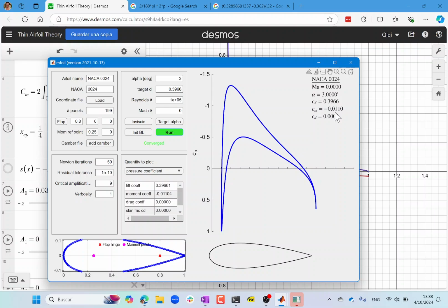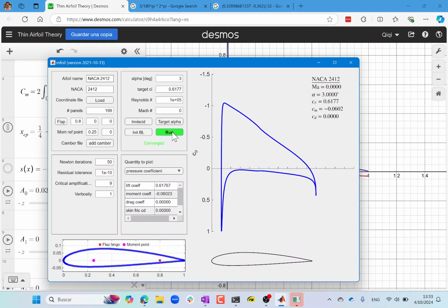And the next thing we'll do is make a cambered airfoil. Actually, one of the most popular airfoils people use is NACA 2412. If you type NACA 2412, you get an airfoil that is probably one of the most common airfoils you would see. So what do the 4 digits mean? How many people are familiar with what the 4 digits of a NACA 4-digit airfoil actually mean?